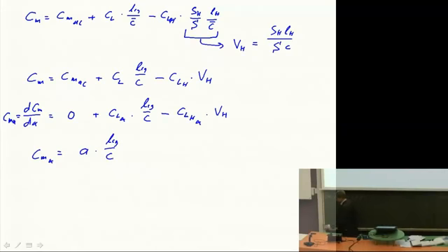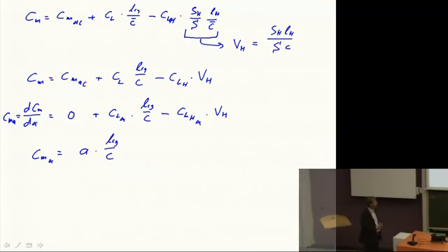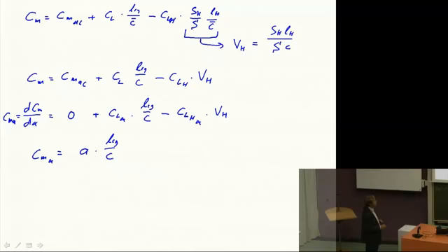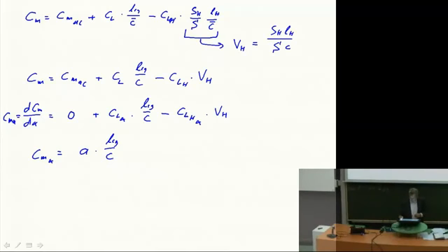But for the horizontal tail, we do not have the change of lift of the horizontal tail as a result of change of angle of attack of the complete aircraft, because that's something they didn't measure when they measured the airfoils, because they didn't know how we would use it in the airplane. But there we do the same trick as we did in the atmosphere calculations with temperature and altitude. We say, okay, what do we know? We know the change in CLH due to the local angle of attack. That is just something that you get when you take the airfoil from the book, you ask the aerodynamics guys, and they will give you this.